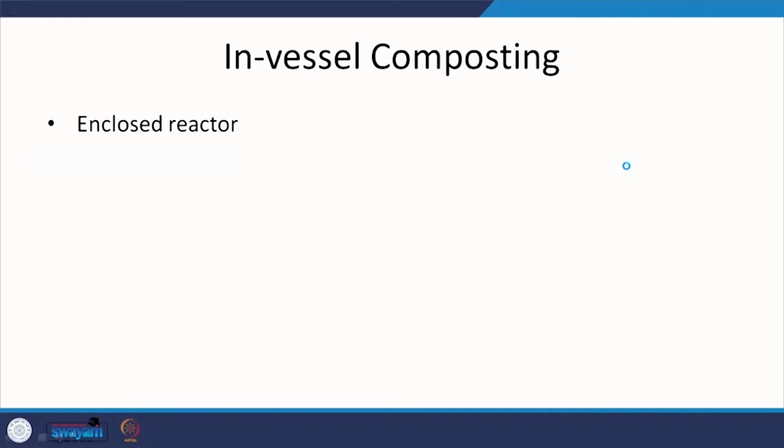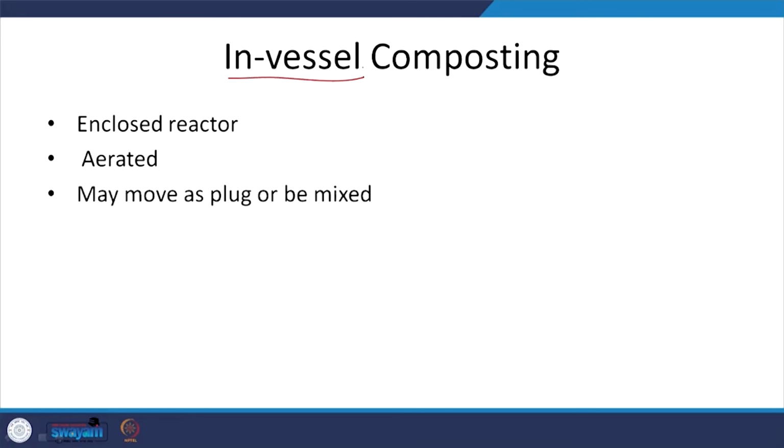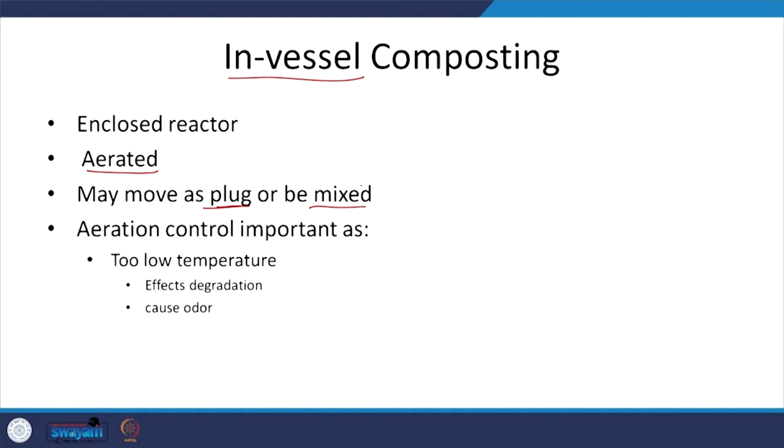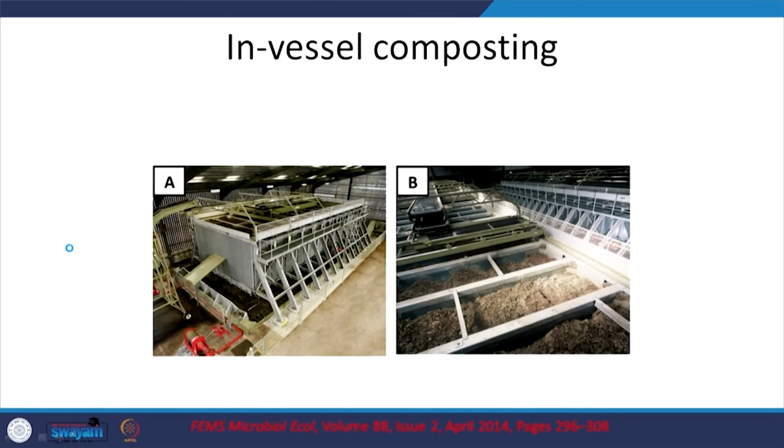So, in-vessel composting is something that can be done, as in you are going to have a reactor, in vessel, not open to the atmosphere, which can be aerated and it can be moved, such that it is either plug flow or mixed, depending on how you design or maintain it. If the temperature is too low, it will affect the degradation and it will also lead to odor, because of the kind of microbes that thrive when the temperature is too low. Thus again aeration and relevant control is required. So, here you have different kinds of in-vessel composters.